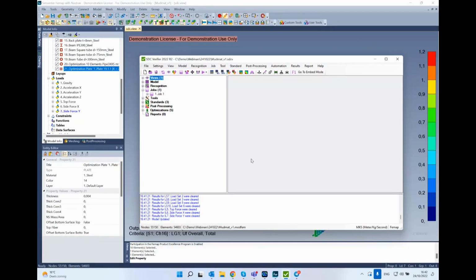I understand your question. Yeah, that's a nice suggestion, but we want to keep the logic the same for all of the types of optimization. If we do this with beams and we run it through 7,000 shapes, it's going to be very time consuming. And the same here. We want the user to define a limitation. So you can set thicknesses with plate thicknesses, it's not that hard because you basically know that it can be from, let's say, 2 millimeters up till 20 millimeters, but not significantly more. So maybe that's something to update for the future.